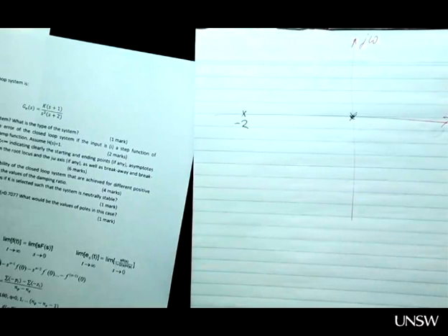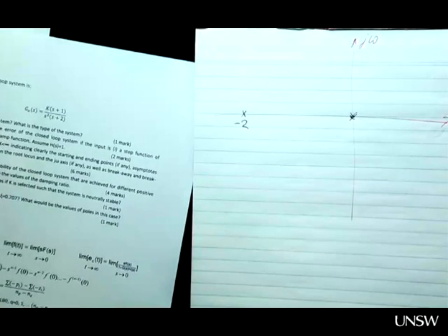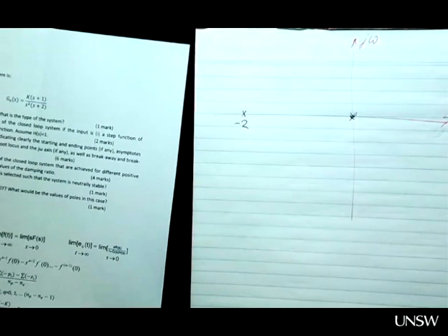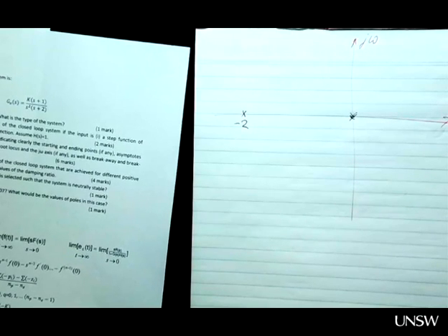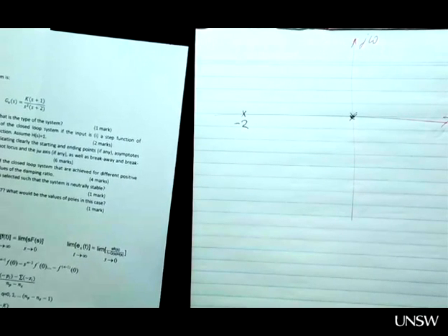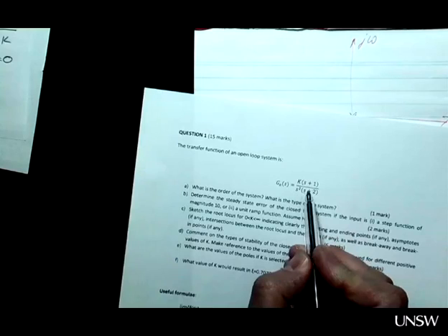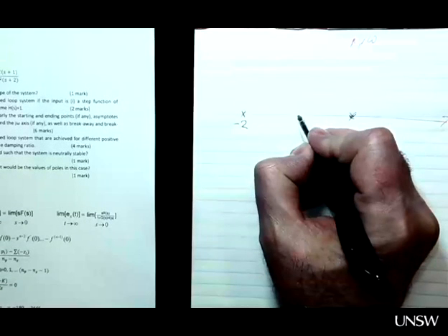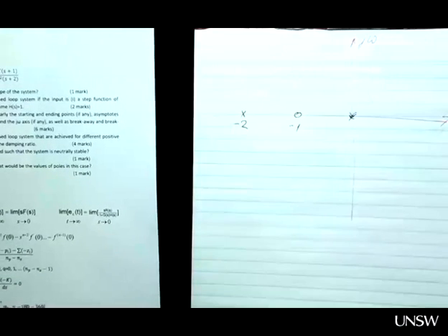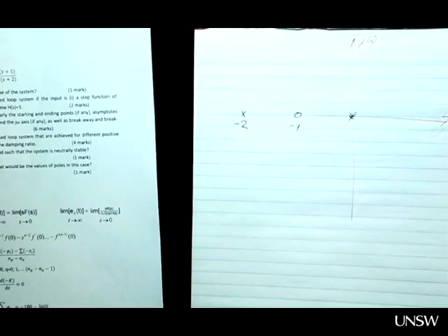Now, let's determine those points where the root locus finishes, where k equals infinity. Those points are the zeros of the open loop transfer function. So we have only one, at s equal to -1. So here we have a zero. So 3 poles, 1 zero. Now you can already guess that because there are more poles than zeros by 2, 2 of the branches of the root locus will end up at infinity. If you're not sure, wait until you apply other rules.